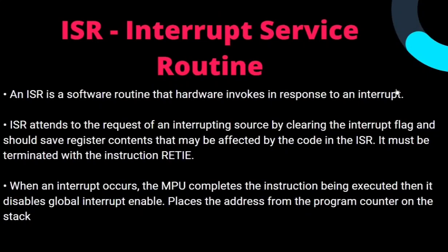ISR, what is an ISR? What is the interrupt service routine? An ISR is a software routine that hardware invokes in response to an interrupt. An ISR attends to the request of an interrupting source by clearing the interrupt flag and should save register contents that may be affected by the code in the ISR. It must be terminated with the instruction RETFIE.